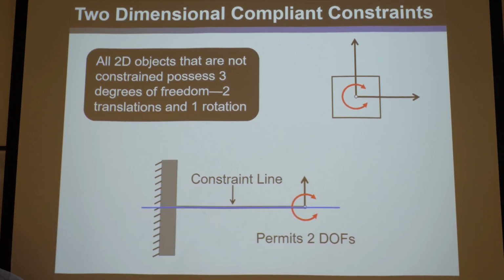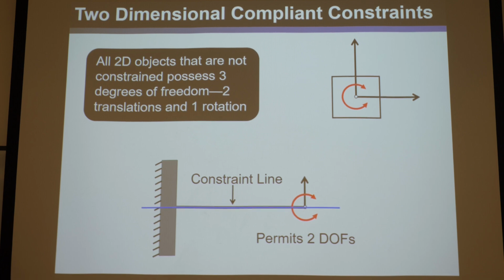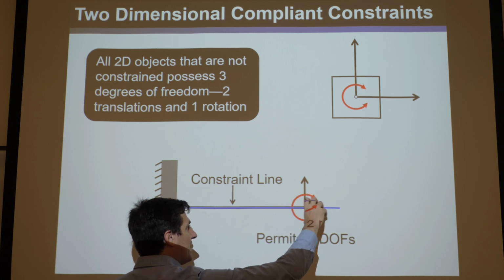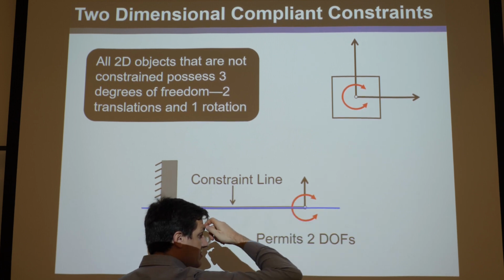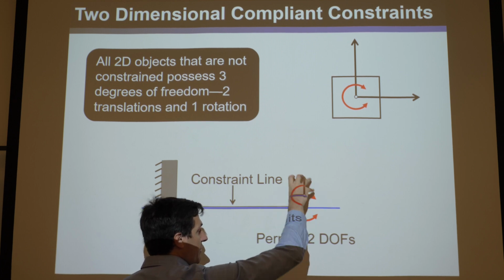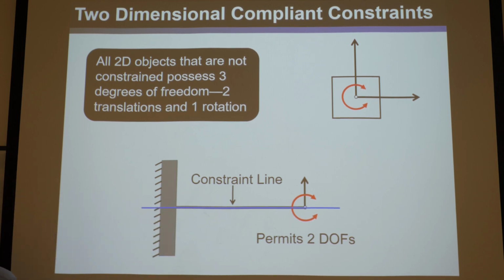Now, of course, that's not true, but it's a nice approximate model because there is a finite stiffness to this, and this can buckle, and even when you pull it in tension, there's, like I said, a finite stiffness to it. And the 2 remaining degrees of freedom aren't infinitely compliant. They do have a stiffness associated with them, but it's reasonable because they're an order of magnitude less stiff.